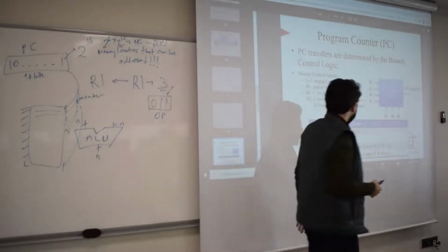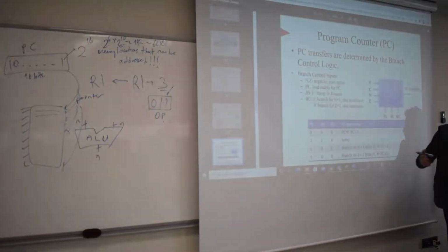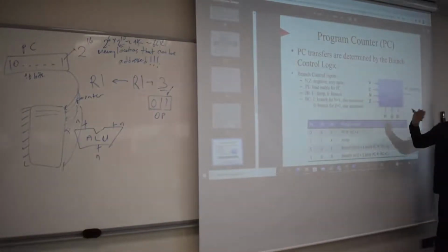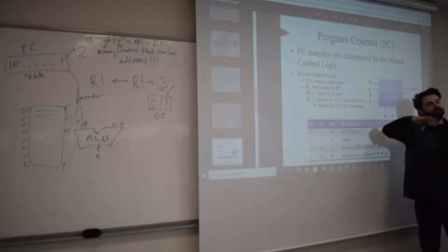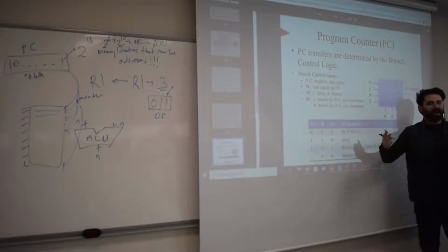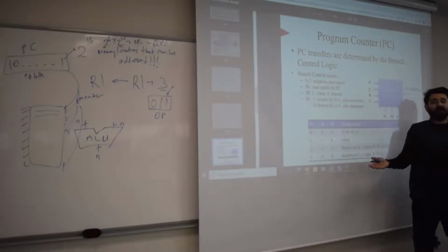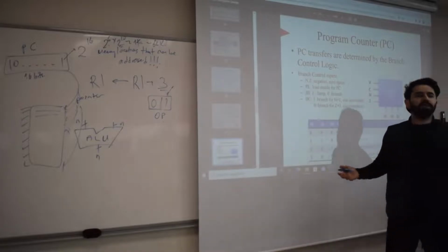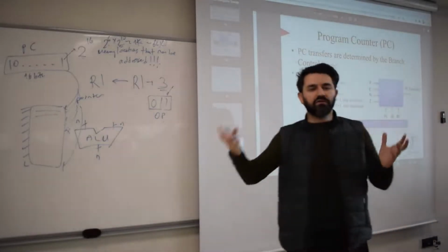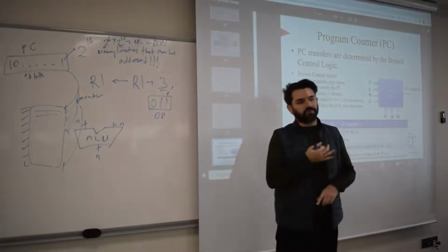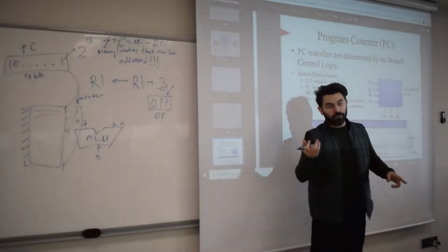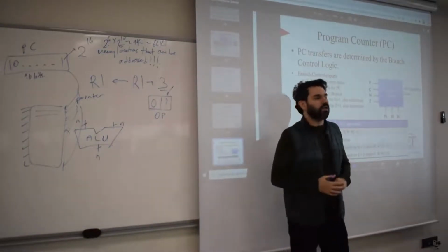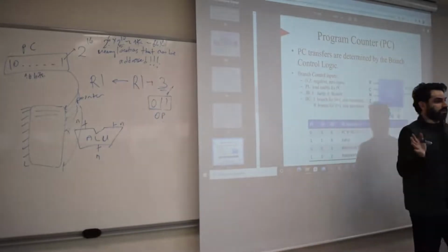So we came up with this control logic because that control logic was not part of our previous control. Remember the previous control, 16-bit long? We didn't have those bits in there because we didn't have any control instructions. We only had simple instructions, mostly register type. Add instruction, subtract operation, shift operation, logic operations. These were what we had in our world.